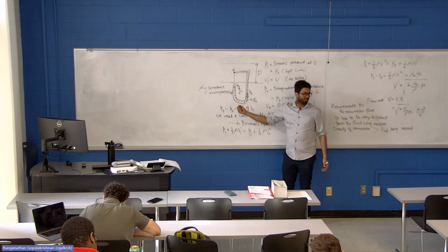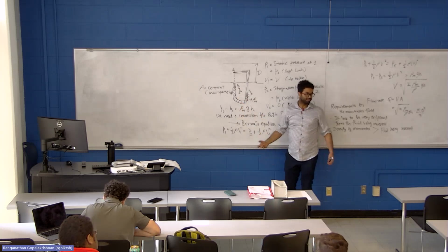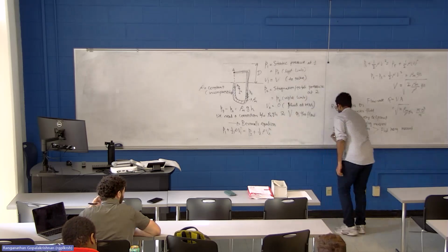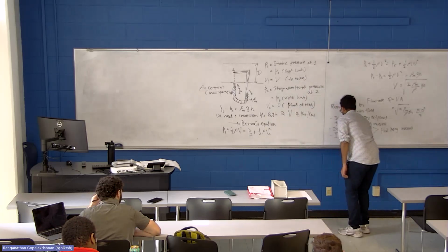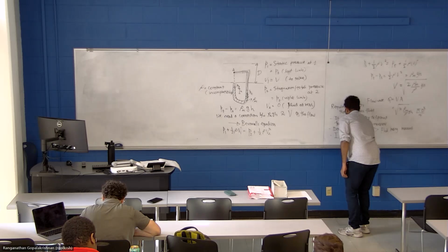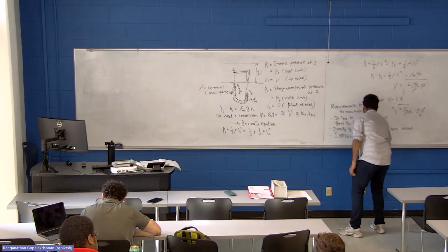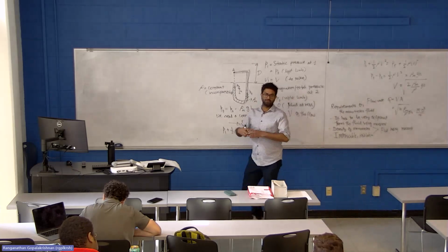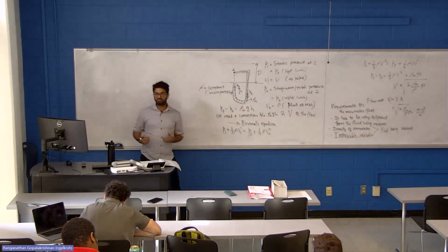Basically, it can soak up CO2 and turn into soda, where your pressure reading will not reflect the flow. So the other requirement is they have to be immiscible and insoluble in each other. You can't have them mix and form a new solution. They have to be immiscible.